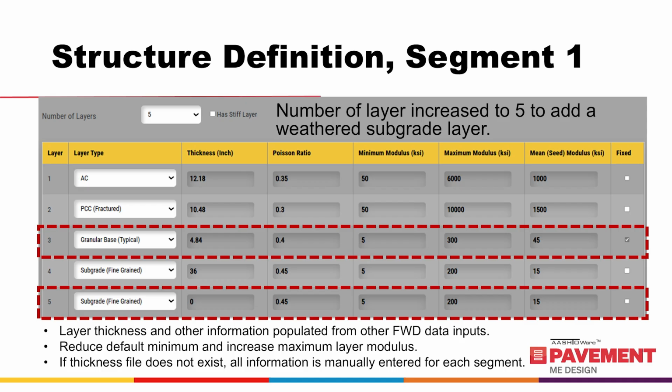However, for back calculation, 2 subgrade layers can improve on the results by decreasing the difference between the calculated and measured deflection basins. The 2 subgrade layers are typically a weathered soil strata at the surface of the subgrade and the natural or non-weathered soil strata.